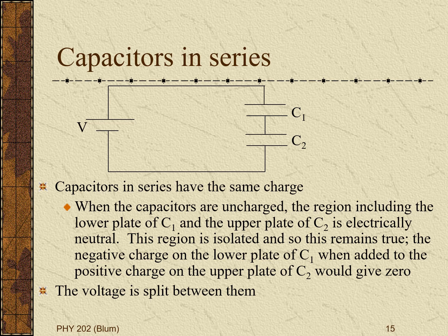Now we are in series, so there's some push of voltage on C1 and some push on C2, and the push of the two individual capacitors adds up to the total push. So the voltage is going to be split, whereas the charge is going to be the same.